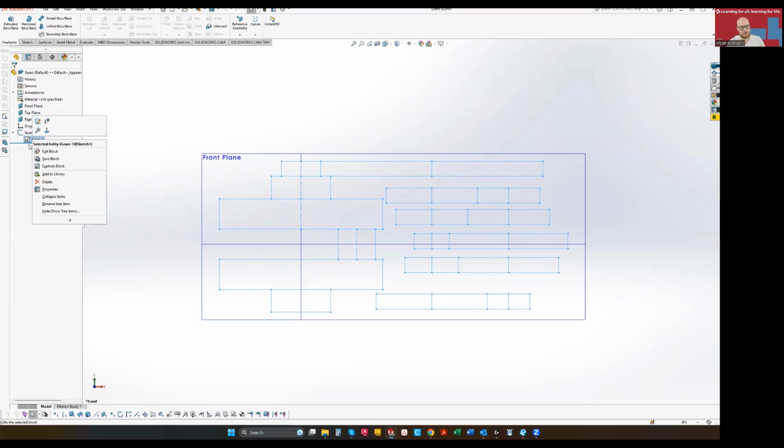You should be familiar with blocks somewhat because that is how we set up our AutoCAD title block. So if you want a refresher on the nature of blocks, you can skim through the AutoCAD title block creation video. Blocks in SolidWorks function very similar, if not essentially exactly the same, as blocks in AutoCAD. So with that in mind, we can edit the block or explode the block to utilize the geometry. In our case, we are going to be opening up additional sketches and then converting the geometry to create the features that we're going to use.